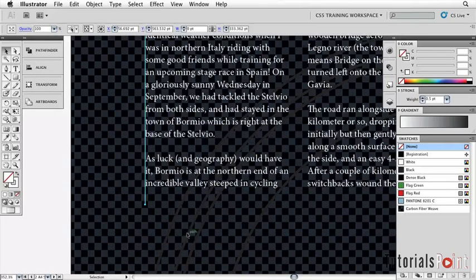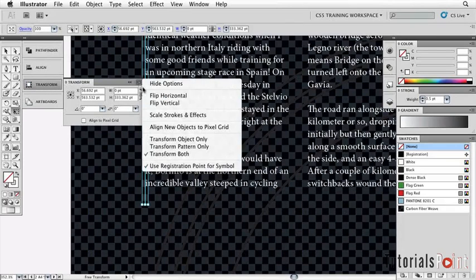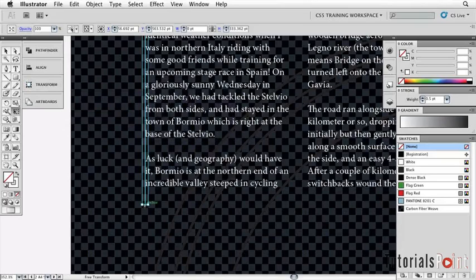So in fact, if I go to preview mode here, we can see how far that line comes down. Now we can go to free transform, and don't forget, to be safe, let's go to transform here and make sure that in the flyout options, stroke and effects is not turned on. Then we don't accidentally scale the stroke from the half point that it currently is. Just want to keep pointing that out to you so you have it in your mind. So I'm just going to drag the anchor point up here and drag it until it lines up with the baseline of our type as it stands.